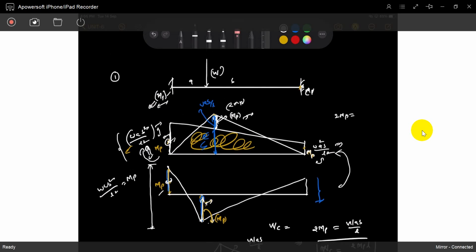If you apply the load, it will give the bending moment diagram like this. It is increasing like this. Once this location reaches the hinge point, a plastic hinge develops, later it will reach this hinge, later it will reach the next hinge. Okay, understood? So that's why the section reaches MP. The bending moment diagram is the same, because the distribution is the same. Up to failure, even if the load is increasing, it will give the same bending moment diagram. The W is changing, that's it. Bending moment is WL by 8 or something, with W changing. Understood? The bending moment diagram is the same up to the failure.